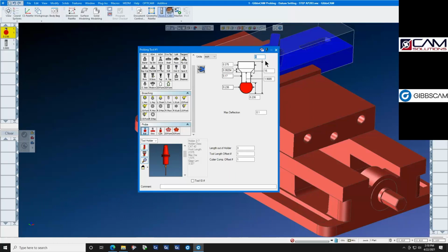This probe that we have described here is the standard 6mm by 50mm Renishaw probe that comes with probably 99% of all machine tools that are shipped here in the United States. You either have a 50mm or 100mm. And we can zoom in and, of course, look at that probe and the stem and the stylus.